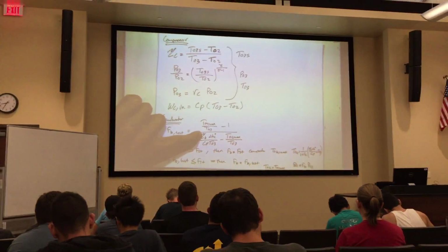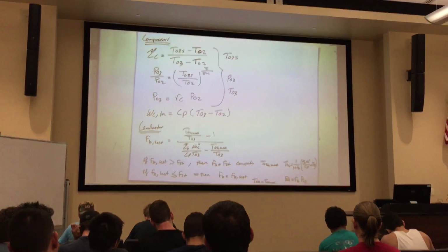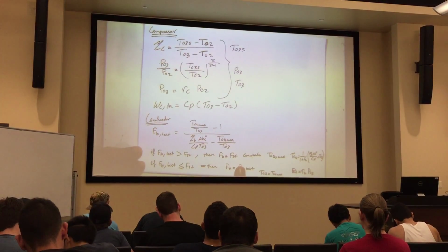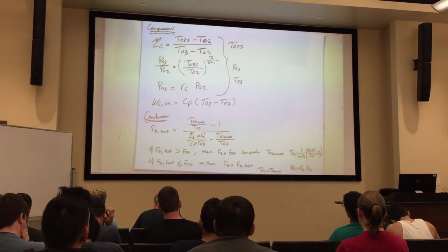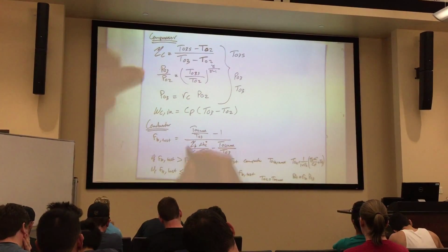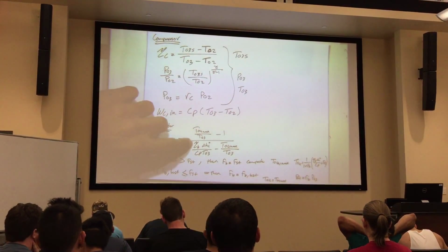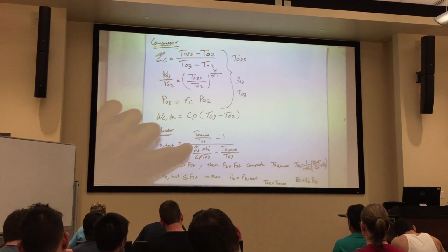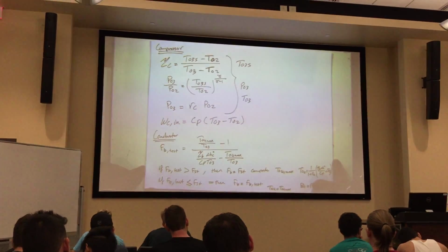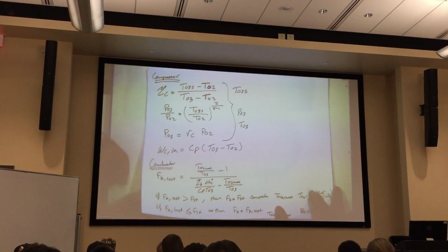So once you know this value and the heat of combustion of the fuel that you're using and whatever the max temperature material for your combustor, you can figure out my fuel to air ratio that I could run through my combustor, and based on that, my Tmax, which is your adiabatic flame temperature as well. But this efficiency, unlike when we did an efficiency characterization for the compressor, is very heavy experimental research to get. And you might be able to pick it up from journals depending on the situations that you're working on.